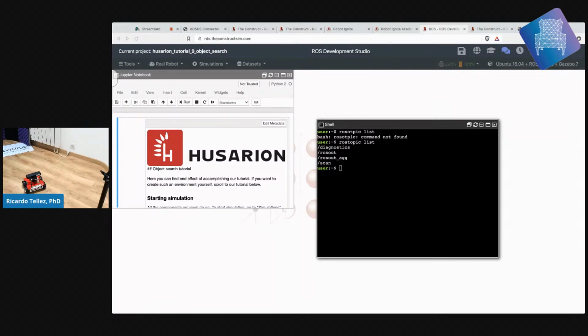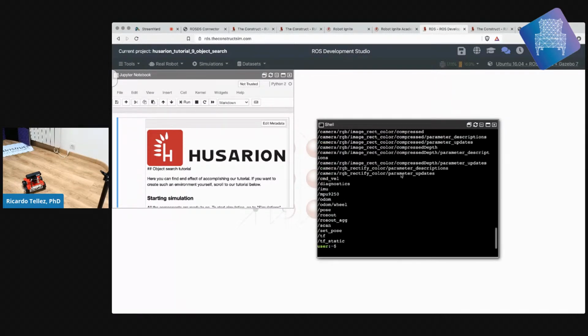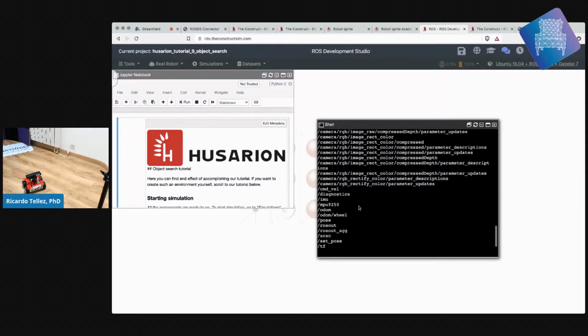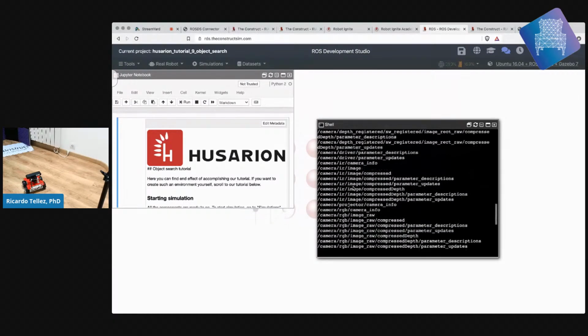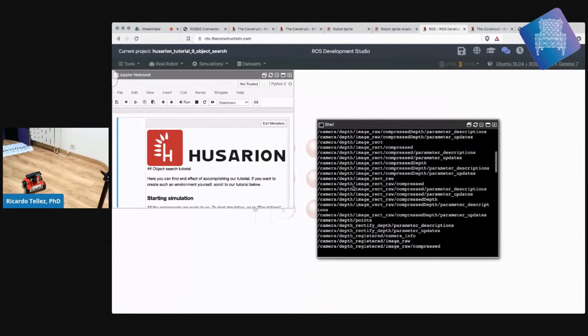Oh yeah, one of the controllers inside the robot has been killed. Let me launch it again. These are the controllers inside the robot itself. Sorry for that. Okay, so I'm launching the drivers there. Now I'm going to do a rostopic list. Now I can see all the topics in there: the TF, the odometry, the velocity, the camera, and so on.